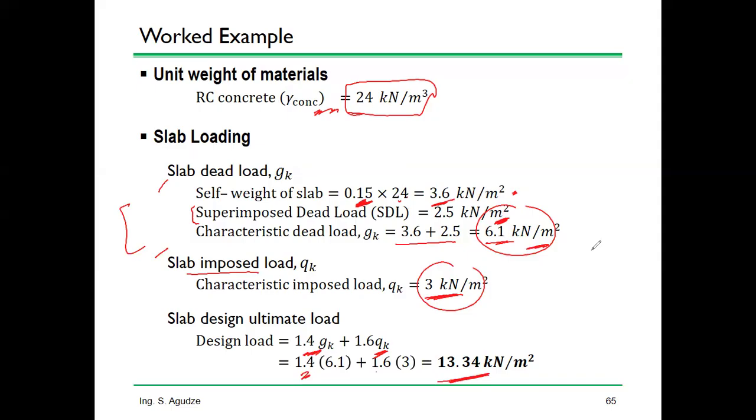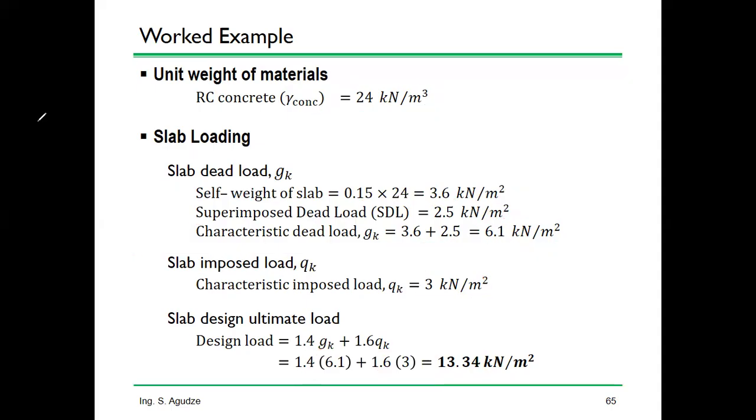Any question? So now with this, we have calculated the slab design load. If there's no question here, remember that anytime you want to calculate the design load, you have to apply this formula 1.4 GK plus 1.6 QK.